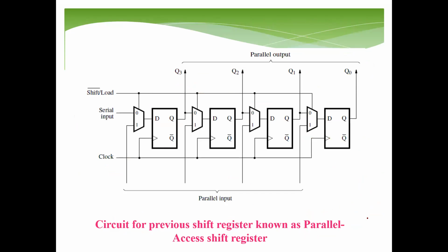Okay, that's it for the shift register. When you synthesize this code, this is what you get. You will get a mux depending on the signal load. If load equals 1, then read from R3, R2, R1, and R0. So if load equals 1, you will read this input. So this will give you a parallel load.